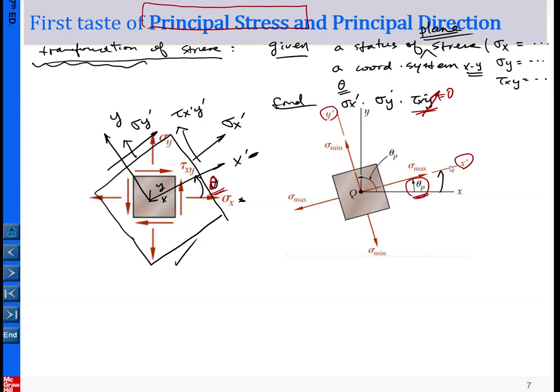And then the principal stress basically describes the normal stress element. So this is the maximum principal stress, and the other one should be the minimum principal stress. So in summary, what is the principal direction? In the principal directions, the shear stress component becomes 0. This is a very special orientation in which the shear stress becomes 0, and this has a profound meaning and applications. We're going to see it when we have more understanding and calculations of the transformation of the stress.